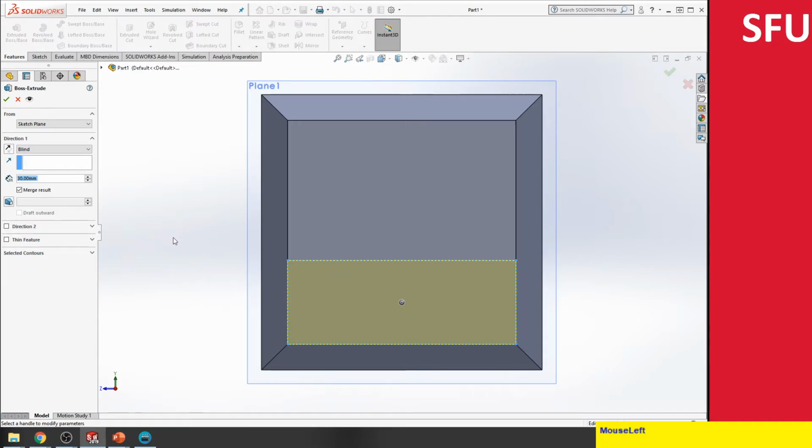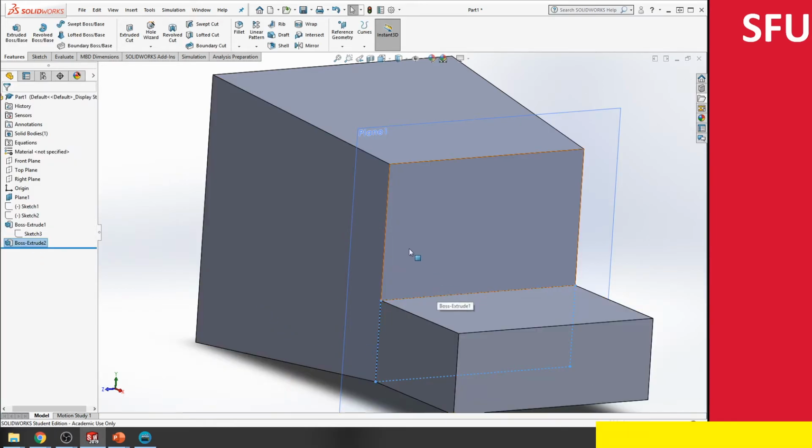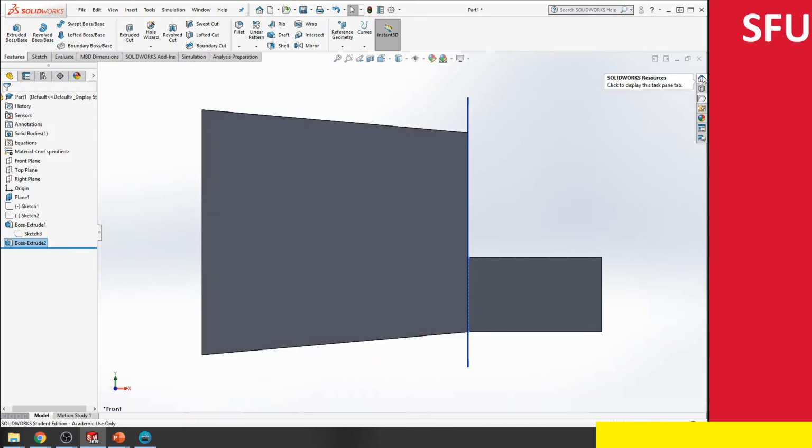So now we can't really see, so I'm going to rotate with my mouse using the middle key. Again, I can give a blind distance over here. Again, I can go up to a vertex, up to a plane. So right now, let's do about 40 millimeters, and then say okay. Now if I reorient my view, with Control 1, I'm going to show you some illustration of what can happen.